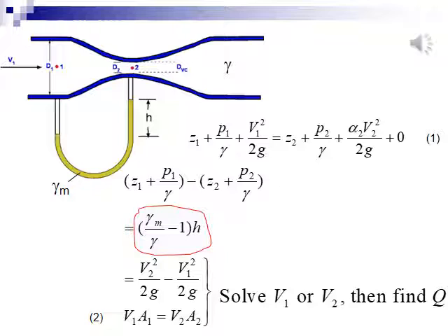Number 1, it gives piezometric head difference, not pressure difference, not pressure itself. Number 2, it measures directly. Yes, just read the value of h. Number 3, it's the difference between its two ends. If the fluid of H is different from the measured fluid, we need a conversion, as I marked with red in the page. Well, the sizes of the tube are given by the producer.